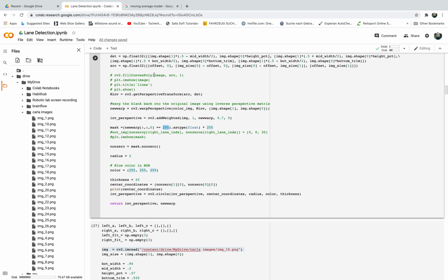So in order to get the real 3D coordinate, you need to do camera calibration, or use the pinhole model of a camera, or use a depth camera to estimate how far that point is from the car. Then, knowing how far the point is from the car, you can reconstruct its 3D location, because you know the XY and you know the depth, and then you can use it as an input for your controller.